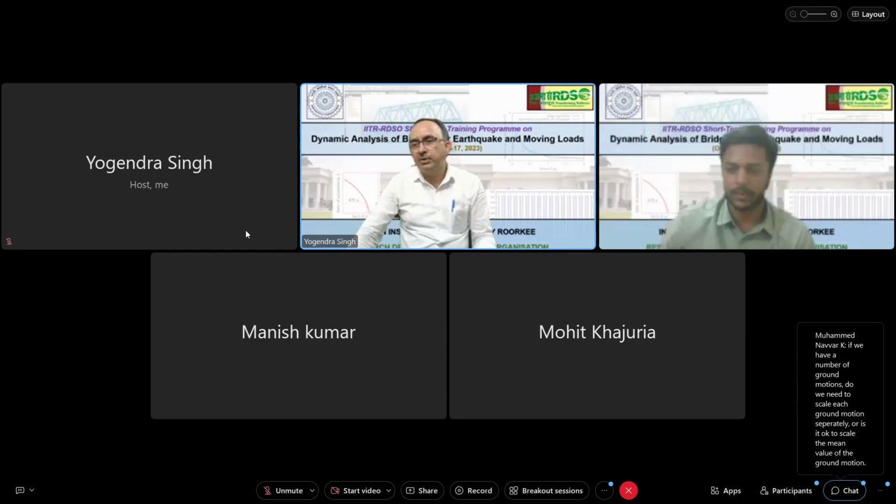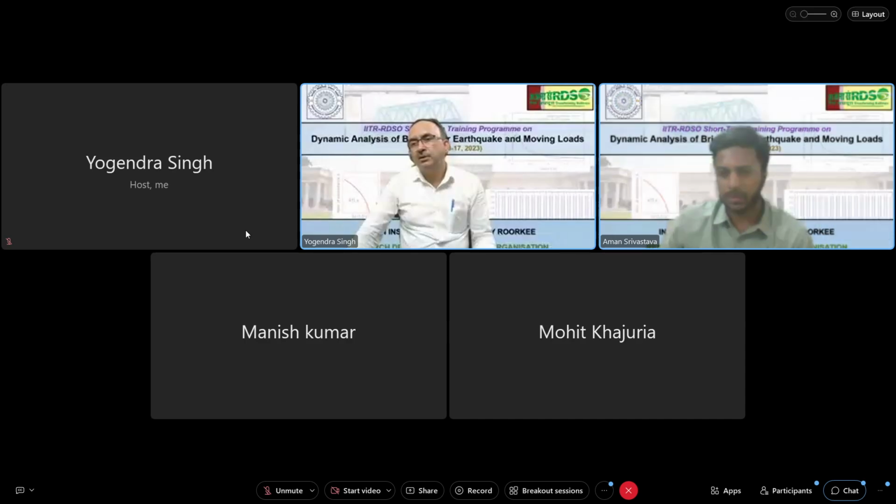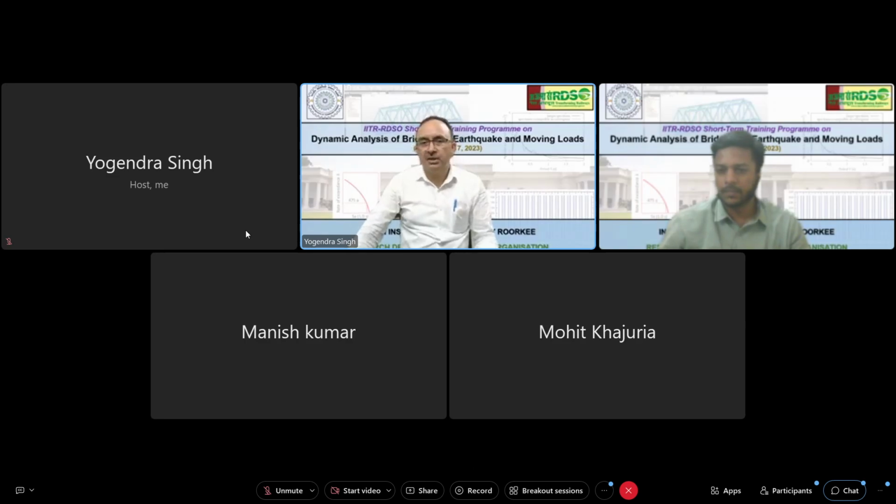Mohammed Nawar asks, if we have a number of ground motions, do we need to scale each ground motion separately, or is it okay to scale the mean value of the ground motion? If you are considering a large number of ground motions, let's say 20 or 30, it is okay to scale the mean and then take the mean value.